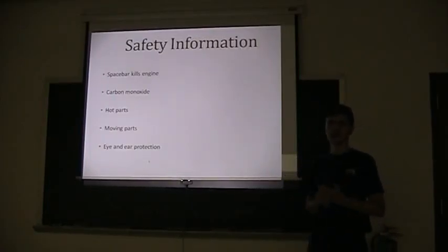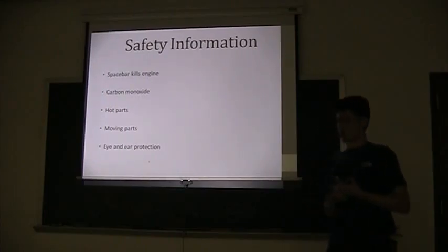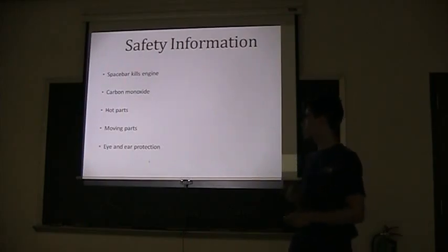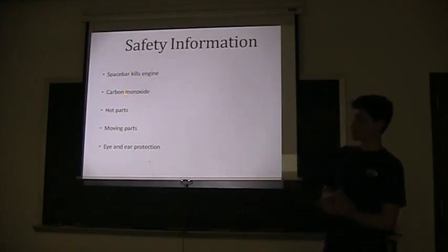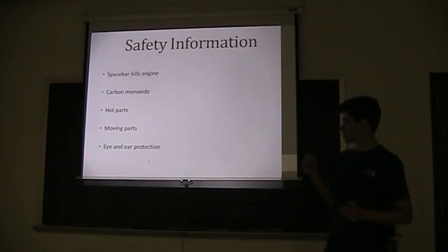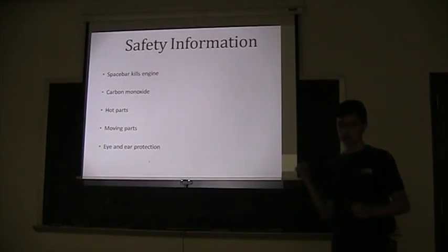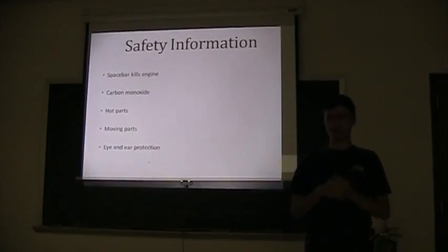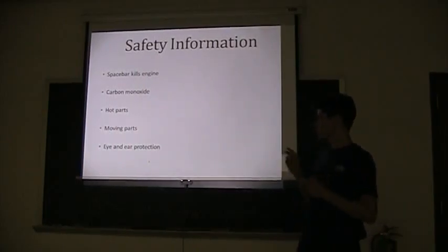Safety information, it's important to note that spacebar will kill the engine. If things start flying or if something goes terribly wrong, you can spacebar and kill it. There's multiple carbon monoxide sensors in the lab, which is right over here. And if the fan is not on to make sure that the used gases are going out and not staying where we're at, you might have a problem.